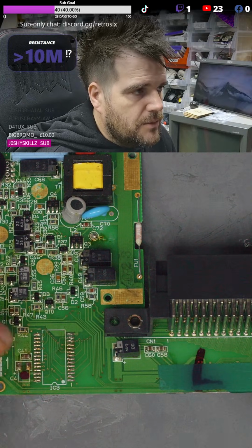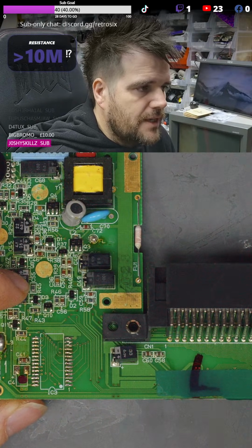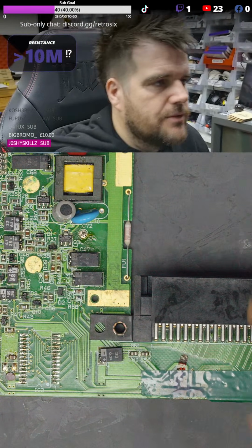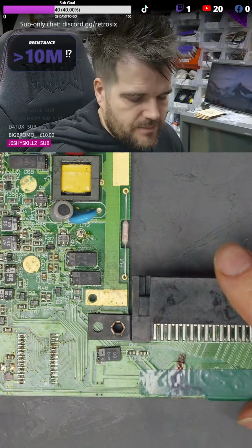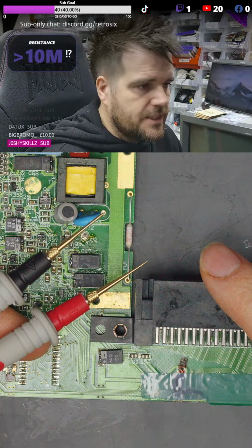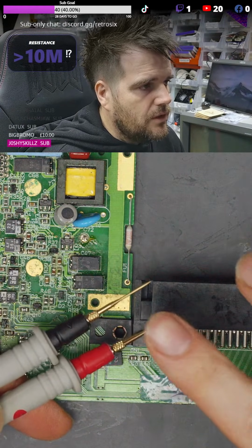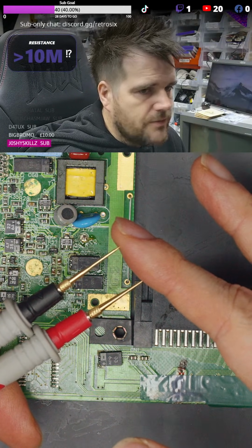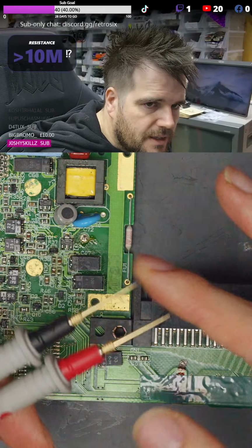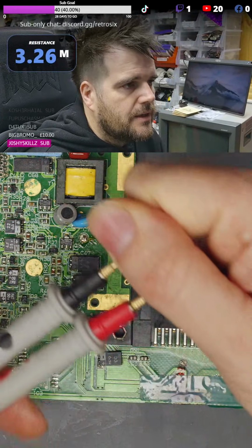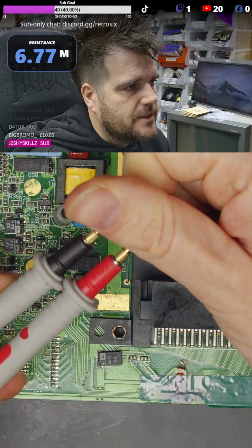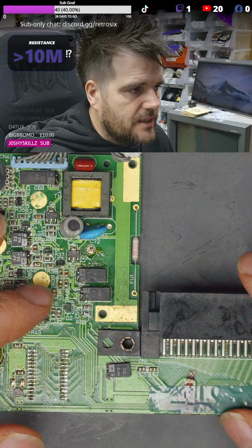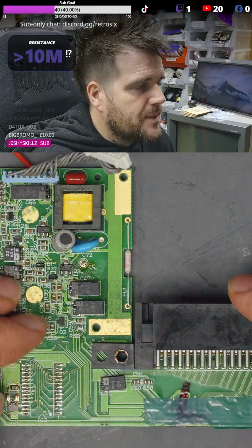And follow with a thermal if you can. I'd recommend thermals if you're going to try and find shorts. It's the biggest method to detect most of the problems. We said obviously resistance mode is good and cheaper, but low ohms resistance mode is expensive to be able to, like say, measure the resistance in skin. Would be 3 million ohm resistance over my skin. But to get low accuracy, you really need an expensive multimeter.